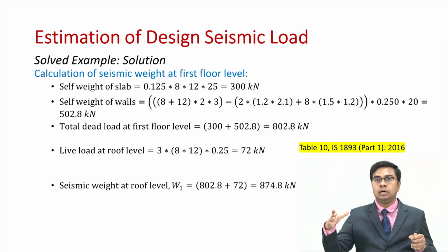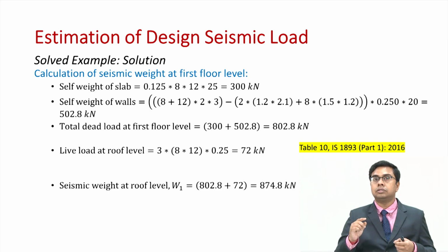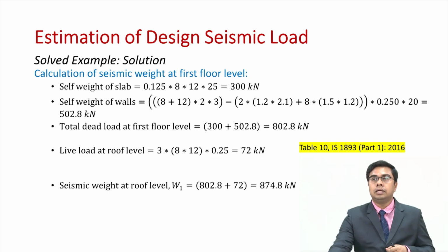Whenever the dimension of masonry wall is such that the width or the length of the wall is less than 4 times of its thickness, then we will call it a masonry column, but that is not the column or the RC column which we used to talk in case of RC framed building. So, that is how in this case, while calculating seismic weight, we do not need any beam because there is no beam as such.